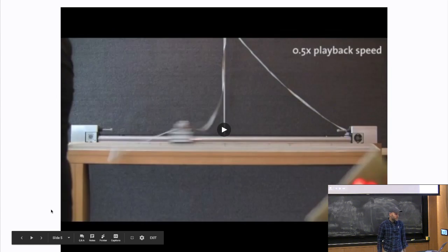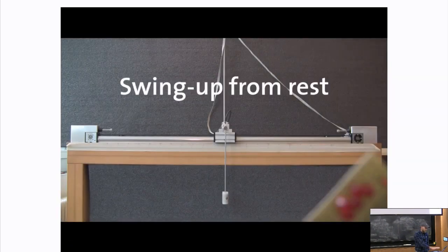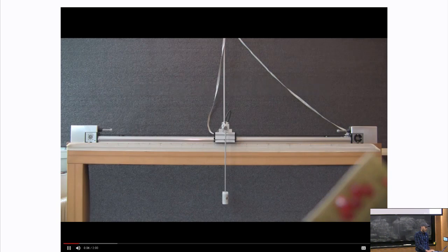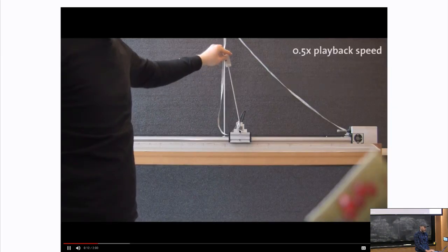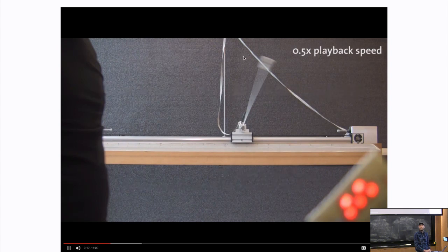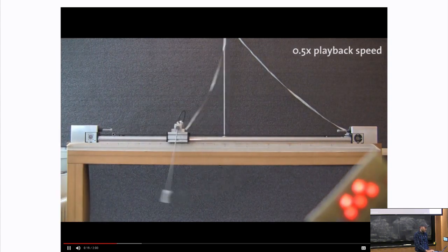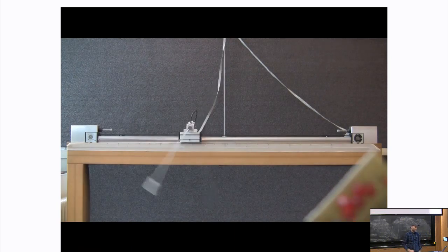This is the cart pole system, which is very similar. It's the famous inverted pendulum. Ignore the particular algorithm talked about here, but just to show what we're talking about with a cart pole. You have control of the force on the base, but you have, again, a passive joint here, and your goal is to swing up and balance it at the top, right? It's kind of extra bonus if you can handle a limited track, because that's more practical for lab, but it imposes some hard constraints.